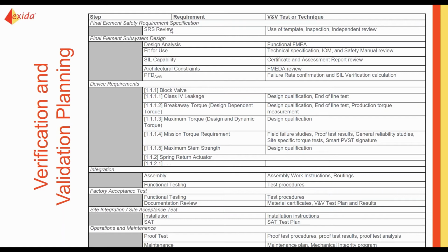So for example, leakage class, that's going to be a design qualification, and most valve manufacturers are going to do an end of line test for leakage, and you'll be able to get their technical manual, their safety manual, their certificate, and request an end of line test data sheet.